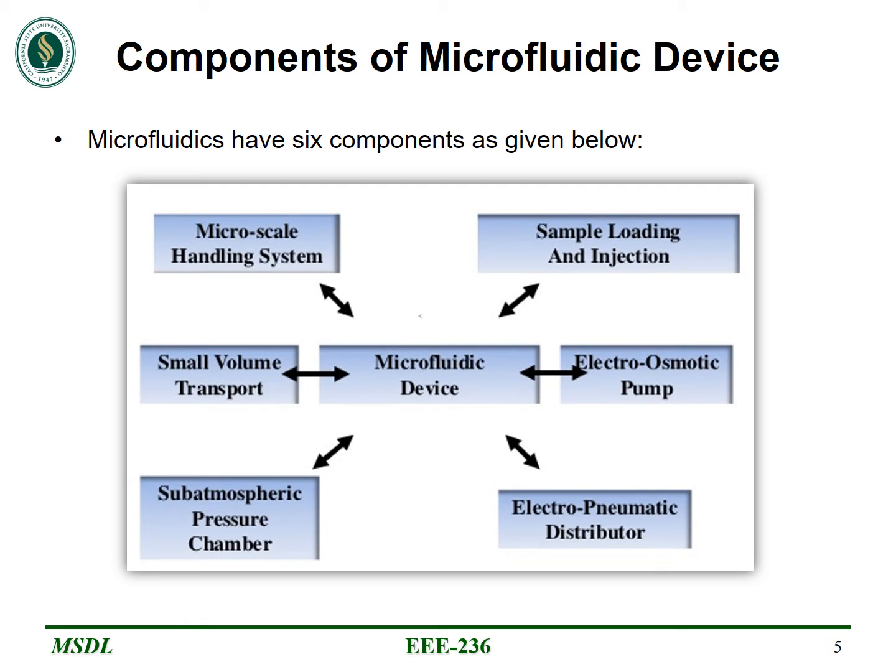Coming to the small volume transport system. It is a solution for moving small volumes of sample through the capillary channels or tubing of a microfluidic device, especially over very long distances. The advantages of this transport system are minimal losses or minimum dilution of a sample, minimal cross contamination between samples, like minimal loss of sample to channel walls and washes inserted between samples.